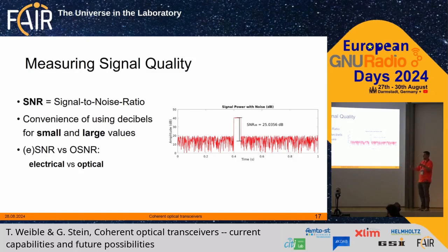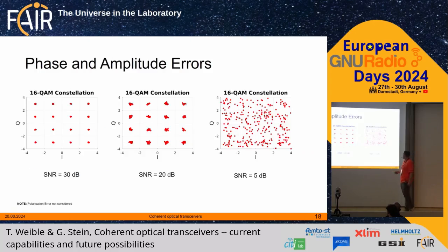You have an electrical connection to your transceiver. Optical is what goes out, the light. And to give you some examples of how the 16-QAM constellation looks when we have a transceiver, I made a simulation, some statistical application based on the Gaussian curve. If we have a good signal-to-noise ratio, which should be high, like the curve I showed you before, the constellation looks like this. So if you put here your mesh, you can still clearly, as a photodetecting system, find out to which bits it belongs.